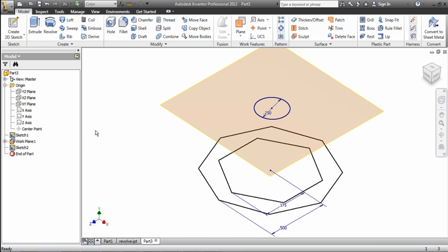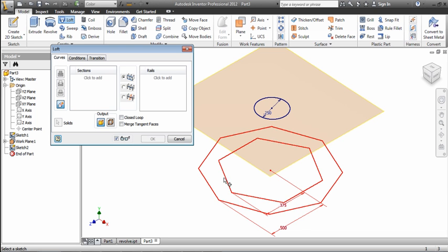Okay. The reason that I'm showing you this is because sometimes you'll have multiple sketches or lines on a sketch, and you want to loft something, but you don't want to loft everything. You want to loft maybe what's in the middle or what's on the outside. So if I click Loft and I choose this sketch right here, notice that it's no longer choosing the profile, it's choosing the whole sketch. So if I click on it, it hasn't actually selected anything because I need to choose, do I want the whole thing or do I want the middle?